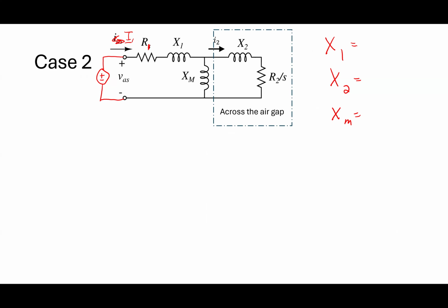So I gave you those values assuming it was 60 hertz, right? So I've got to basically say that it's whatever I had before times 30 over 60, so basically divided by 2, right? So I'm going to have to do that for all of them. Yep, because basically everything's going to change. The inductance stays the same, but the X values are different.